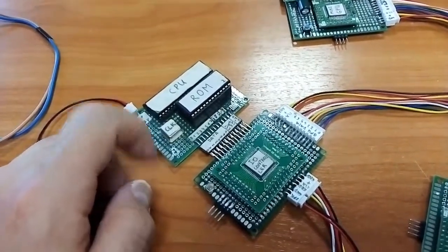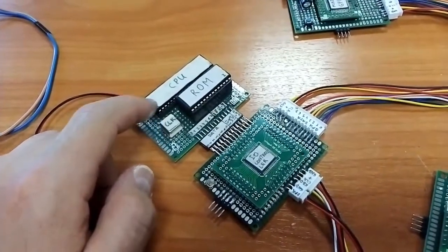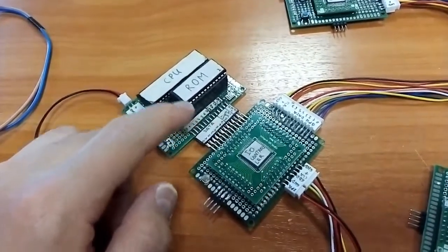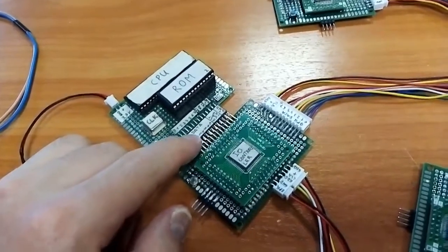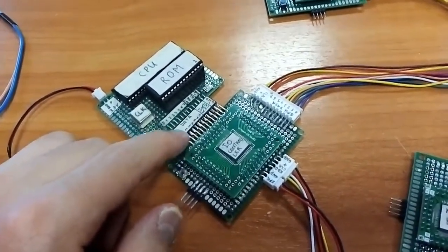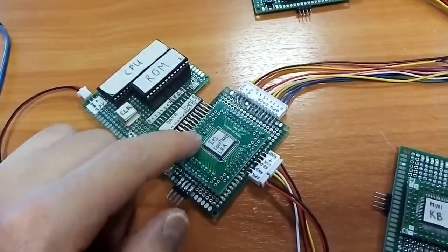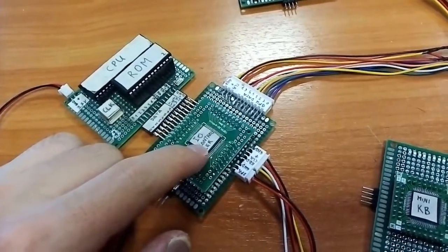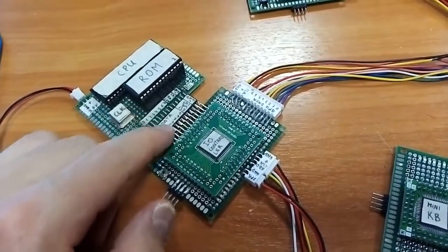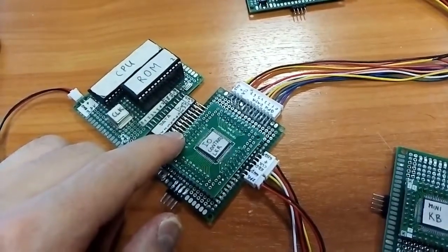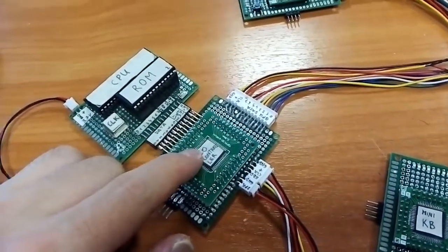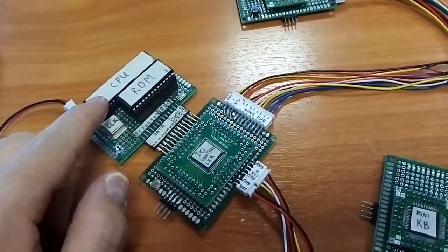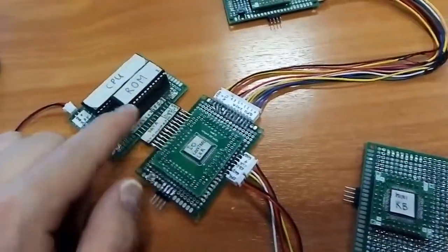And then it understands that it's supposed to send some bytes of data according to the program here. The CPU sends some bytes of data through the output port, these 8 bits, and sends them here to him. When he receives the marker, 4 bytes AA, that means for him that this is the end of transmission. Then the CPU goes to sleep to listen to interrupts from the keyboard, after a key is pressed.